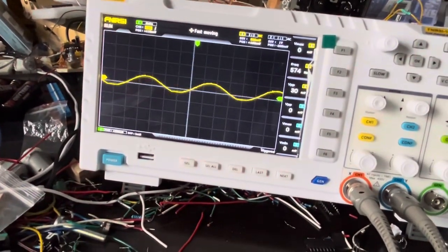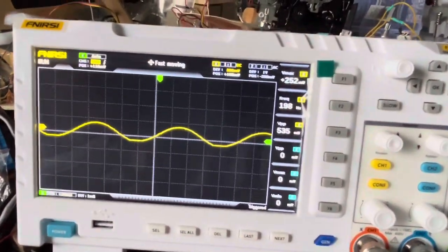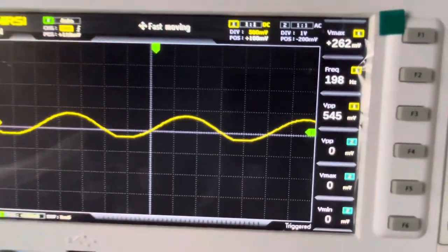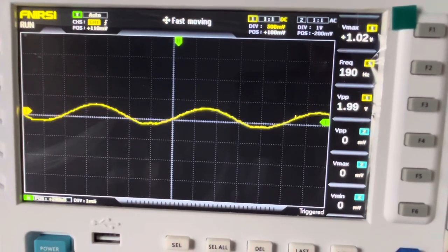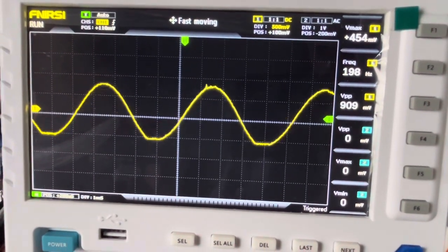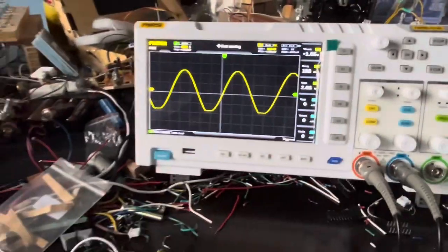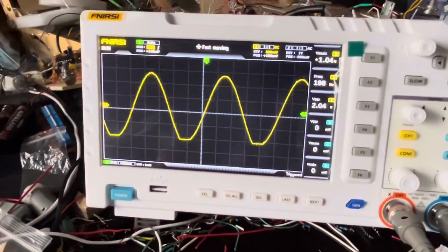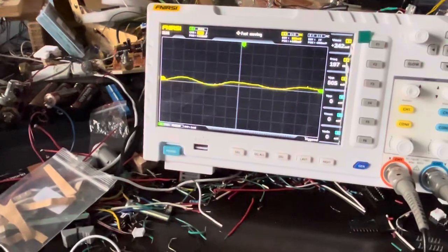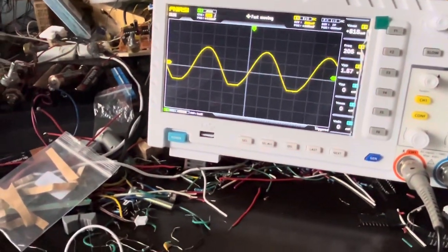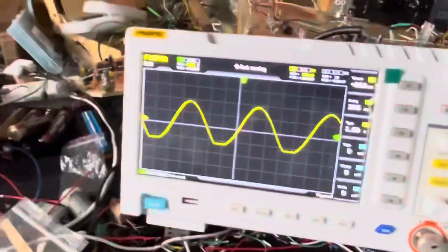I could scale it down to nothing. But here, you can see the peak to peak voltage pretty readily by just a turn of the potentiometer. So this way, I've made my very own sine wave function generator, and you can change the frequency on it by varying this potentiometer. It's a little finicky on the breadboard, but there it is.